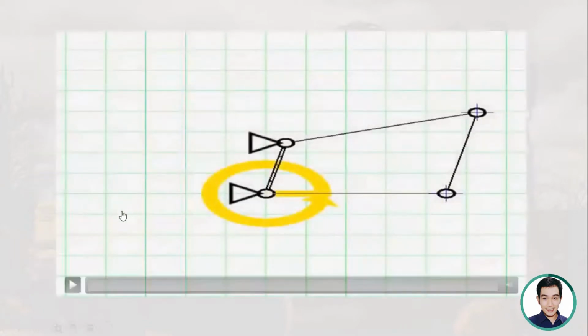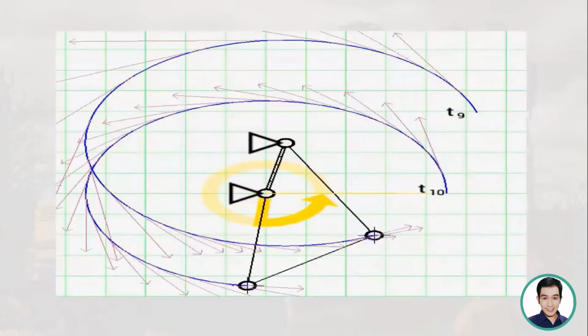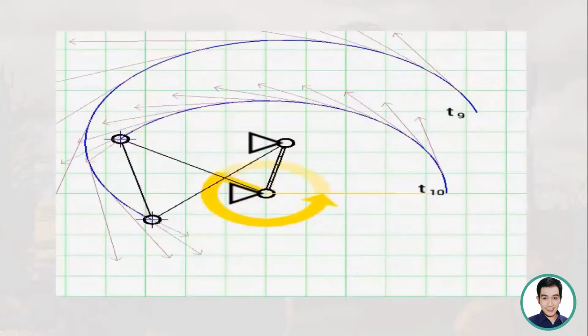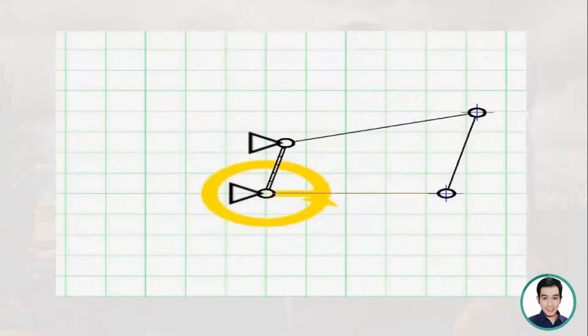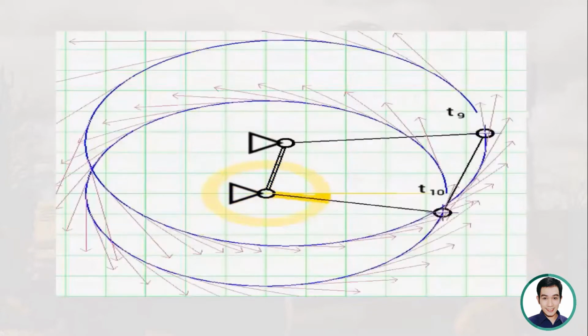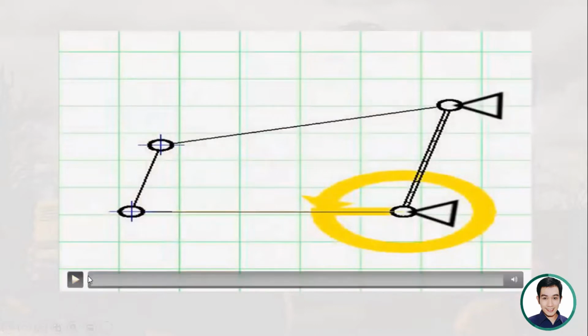And then we have the drag link or the double crank. So there are two complete revolutions. Each of the links adjacent to the shortest link will rotate. So that's a drag link or a double crank. And then we have the last one, wherein the coupler rotates.